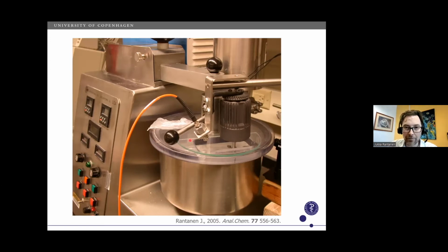So here we have 0.5 kilo of powder being mixed, and then we can add there a granulation liquid and then keep on measuring the process while it's going and without any sampling. So this light source is here illuminating the granules, and then this fiber here is collecting the back reflected light. And this we can use for understanding what is happening in the process.